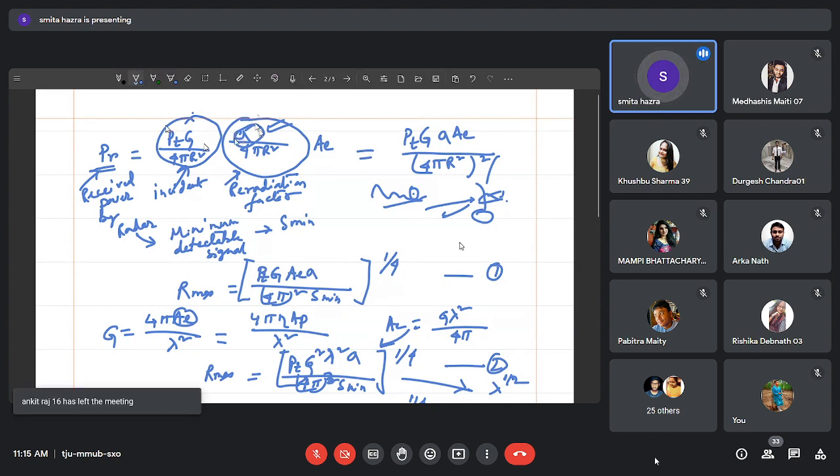Usually we use a large antenna aperture, and sometimes, based on the nature of the operation, if it is a scanning type of operation, it is replaced by the scanning type of radar, that is an electronically steerable antenna, where we can use phased array technology to get quicker scanning. We will consider that when we consider the system itself or the device itself. Okay, so up to this, the first part is covered.